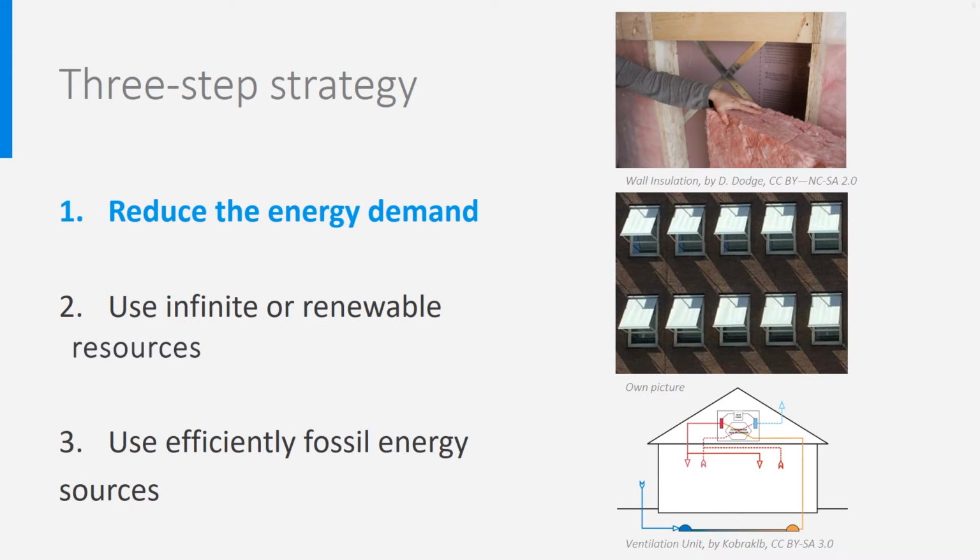Besides reducing energy needs, it is important to mention that you can also reuse energy that's already in the building to reduce the needs for resources. See the picture below. This picture shows a schematic overview of a balanced ventilation system that makes use of a heat recovery system. It takes heat from the warm inside air to preheat cold outdoor air supplied into the building.